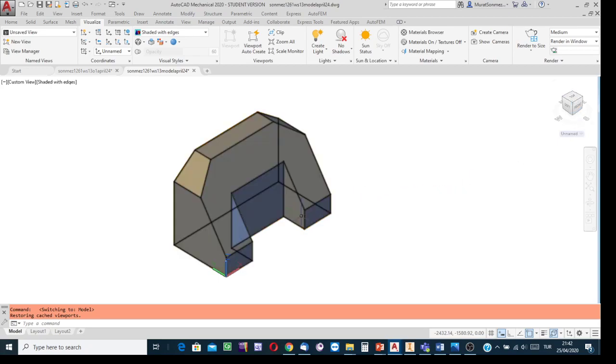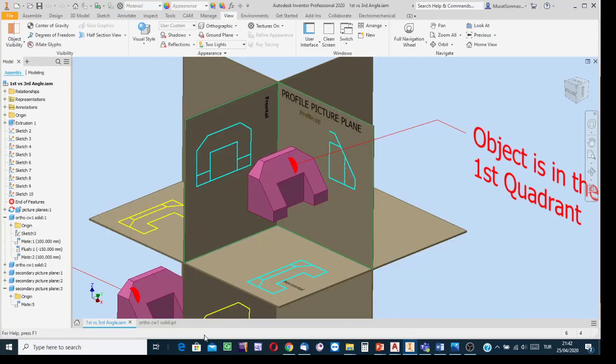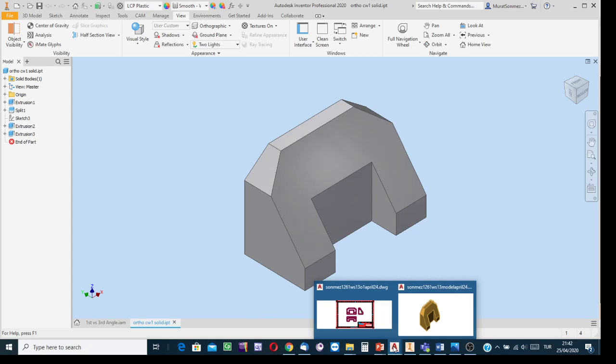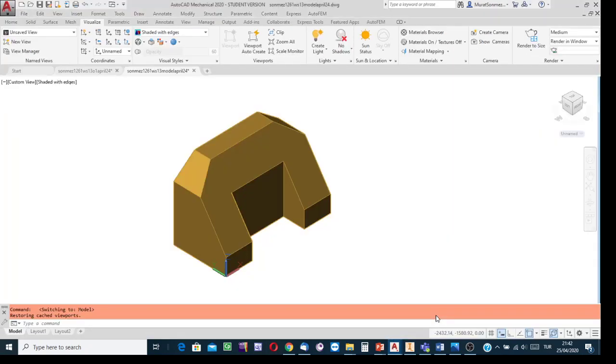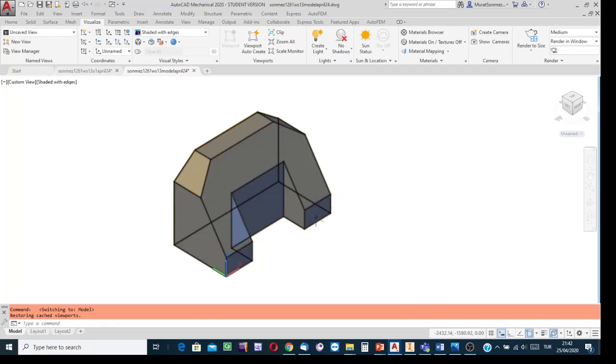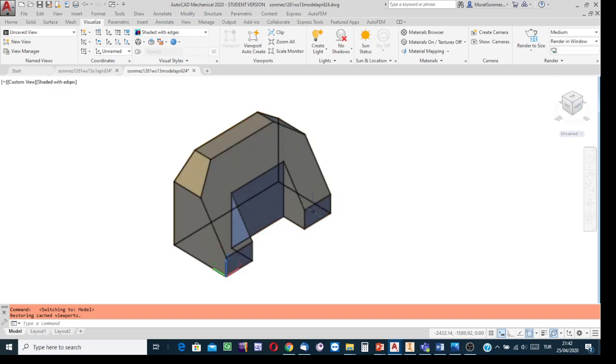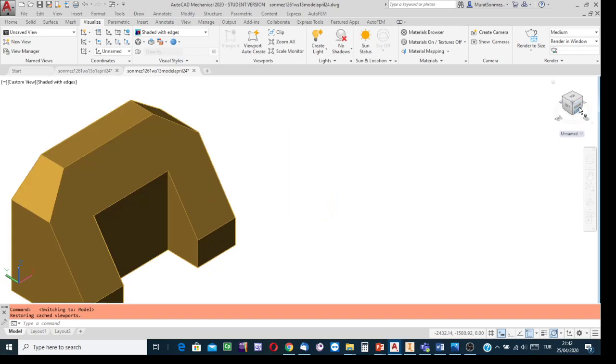Well, in our example, that surface is the most front surface. Saying that this is the most front surface, I said that it is the front side. Okay? Now, my purpose is to create the front side view as the base view. Now see, the front side of the model is parallel to that side of the orientation cube. And see, on the surface of the cube, which is parallel to the front side, which word is written? Front is written.